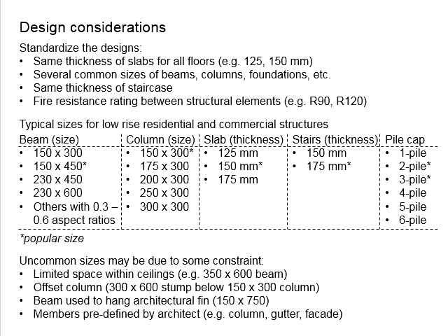A ratio greater than 0.6 is typically not recommended. It will result in a bulky beam section, which increases the width of the beam and provides quite limited contribution in moment resistance. At the same time, the weight of the member increases significantly. This will result in a drastic increase in the amount of reinforcement bar required within the member.